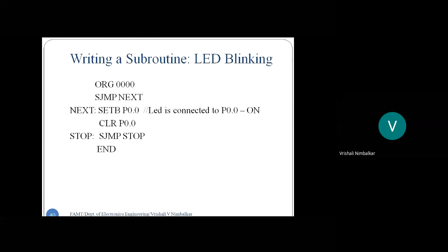And here it is in microseconds. Will I be able to see that? No. 10 raised to minus 6. Something is happening 1 upon 10 raised to minus 6 times. I will find that LED is continuously on. So those changes are not detectable to our eyes. So like this, setting and clearing all of a sudden, one after the other is not going to work out.